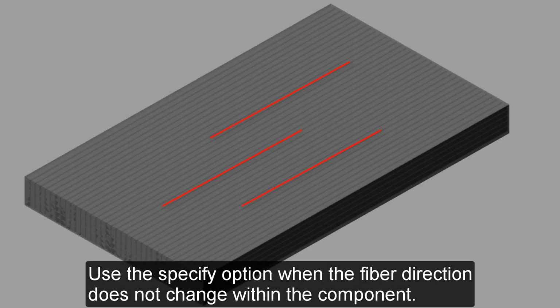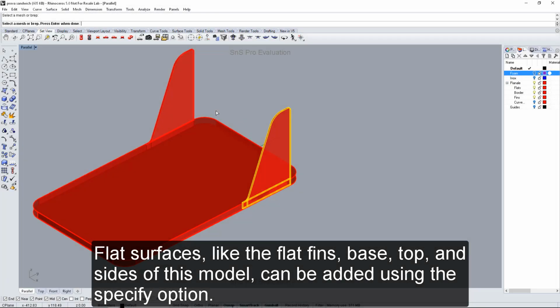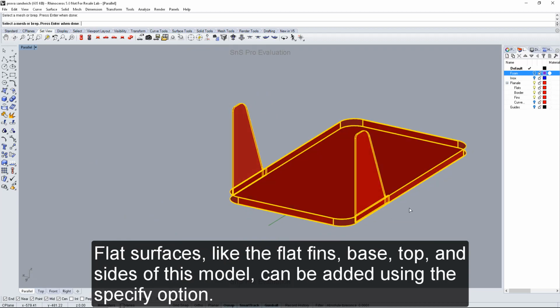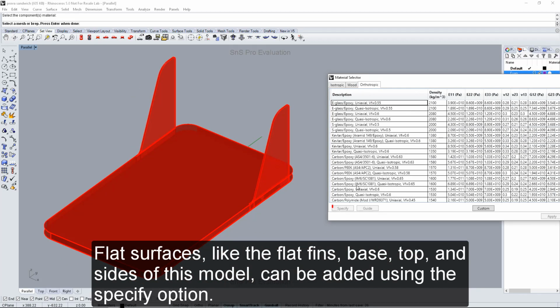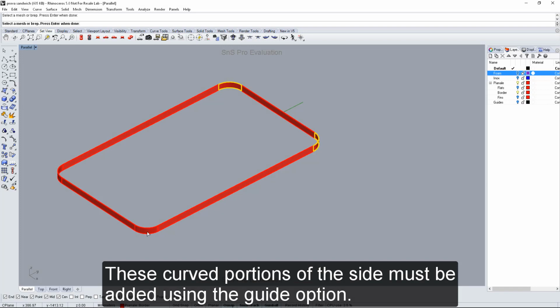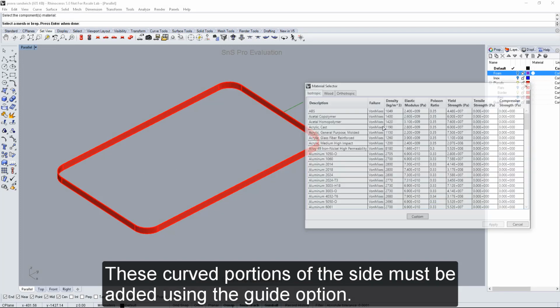Use the Specify option when the fiber direction does not change within the component. Flat surfaces, like the flat fins, base, top, and sides of this model, can be added using the Specify option. If the fiber direction changes throughout the component, as with curved features, the Guide option must be used. These curved portions of the side must be added using the Guide option.